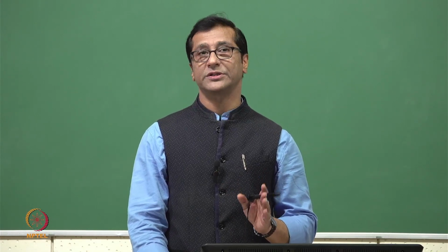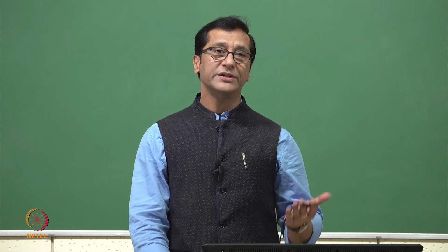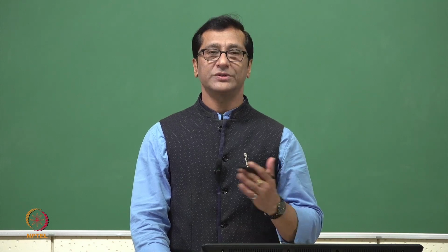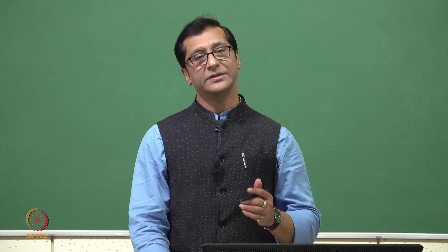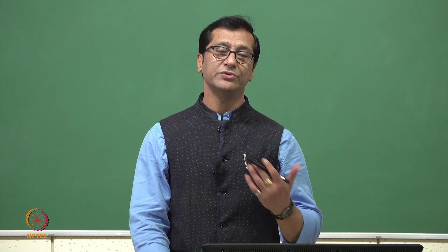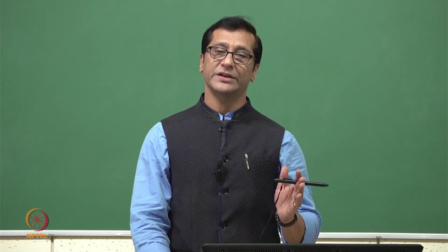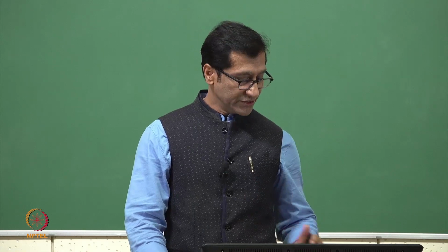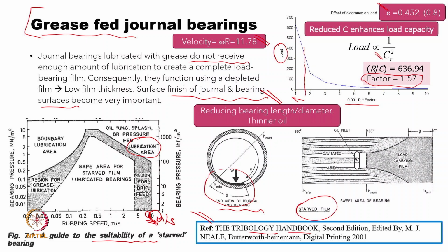If we are able to do it, there's a possibility we can utilize the grease lubrication, or maybe a better grease, or maybe synthetic grease, or maybe a grease with some sort of nano additives, which we will be learning in lecture 15 when we talk about nanotribology, where we use a lubricant with nano additives, so that the results are more favorable and we can dissipate the heat much faster. So this 10 meters can be extended to 15 meters, and this lubricated bearing will be useful for that purpose. So this is what we say.